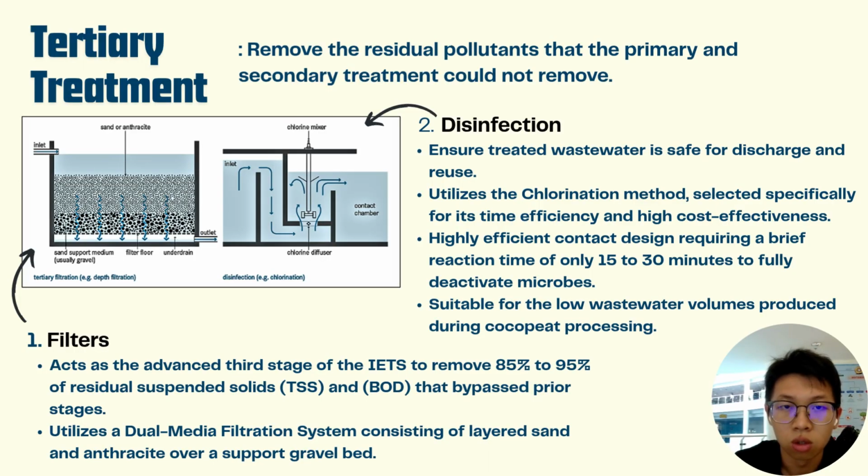For this project, a dual media filter is proposed using layers such as anthracite and sand. This type of filter is suitable because it improves water clarity, has better filtration efficiency, and can operate for a longer period before backwashing is required.